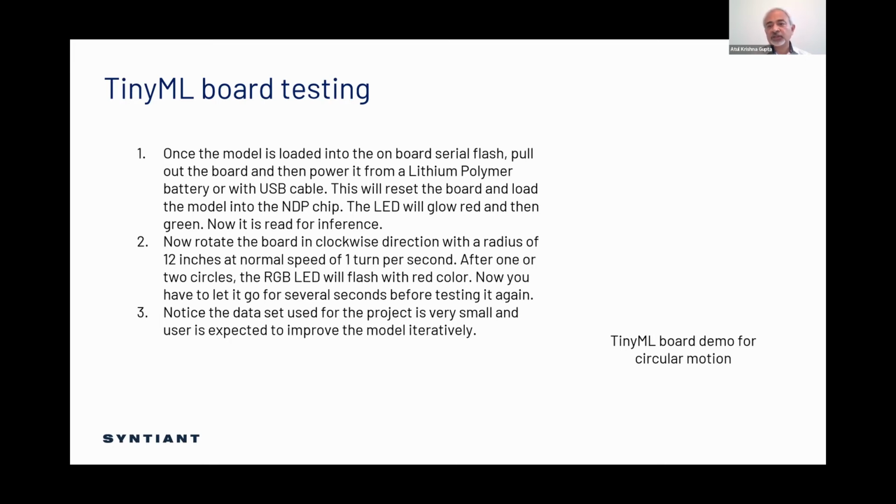So my recommendation is that at that time, you probably have to use a lithium polymer battery. And since the vibrations and other things depend on the packaging and how the board is secured, you may want to make a 3D printed model of the gadget you want to make. So the vibrations, etc., are actually part of the training.